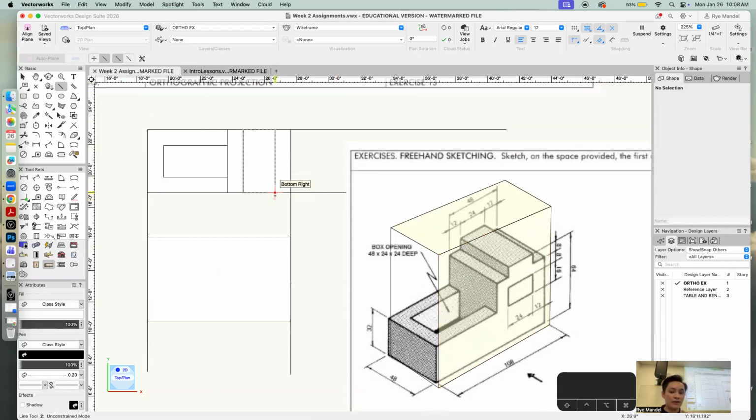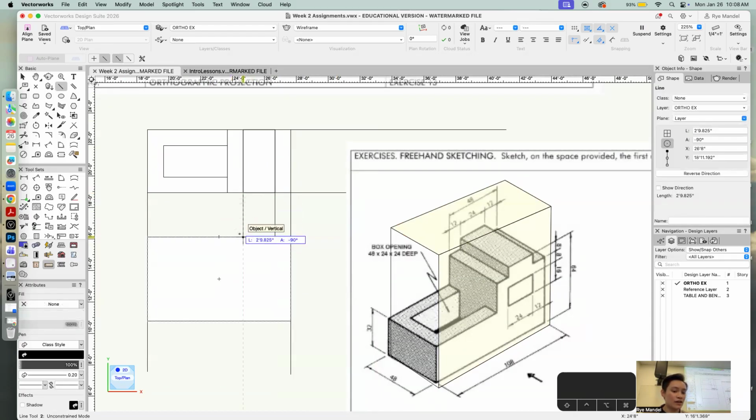The next thing I would do is take these points that I've already created for my ground plan, and create these snapping points for myself, just so I know that my snapping points are there. Then I'm gonna tackle this little box that's right here next. I'm gonna click on this snapping point that I've just created, go down, and type in 8 inches, and then hit shift so that it snaps, and click. Then I create the other one by hitting a line and clicking on the first point, then the second point.